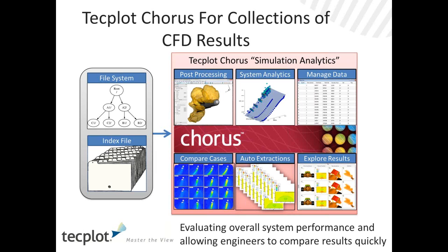If you're a code developer, for instance, the high-lift prediction workshop is one we've looked at before. In that case, they're trying to evaluate how well codes and turbulence models work on a particular flow field to predict the lift of an airplane in landing configuration. And so they had a lot of parameters there related to the type of code being run and the techniques used and the turbulence models, and whether it's transition models, grid resolution. So that would be a form of parametric study.